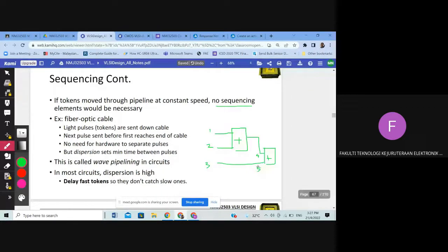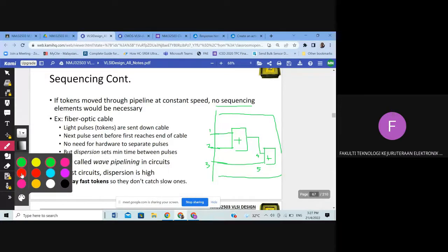Theoretically, let's say this is your system from the outside. We have delay inside the first adder. This is your first adder, A1, and this is the second one, A2. The output of adder number 1 will take some time because there is a delay inside the first adder. The input from 3 directly enters the second adder, A2.